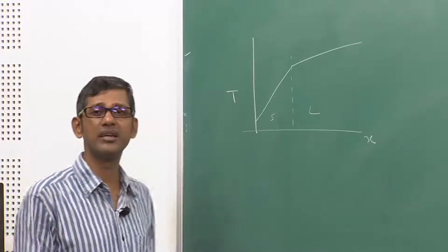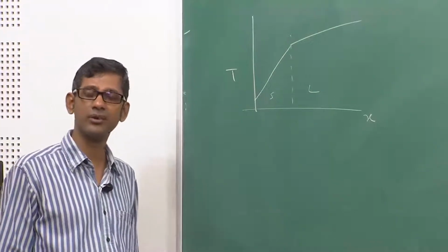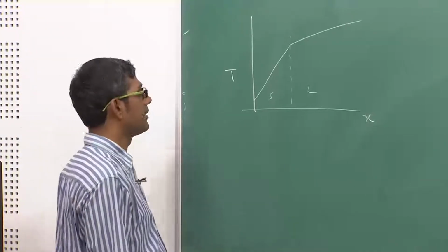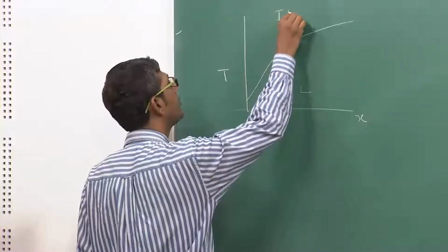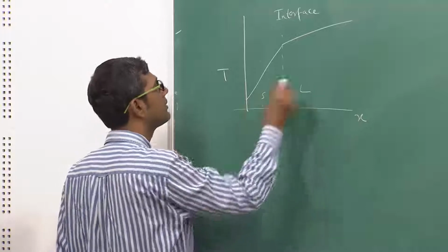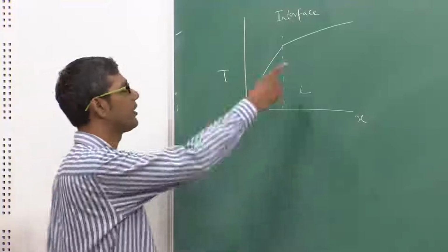Well, let us now discuss how we can develop a mathematical expression for the heat transport in the solid liquid phase transformations. As you see, this is an interface which I have drawn between the solid and liquid, and this is solid, this is liquid. The temperature gradient both in solid and liquid are positive because the slope of these curves are positive.